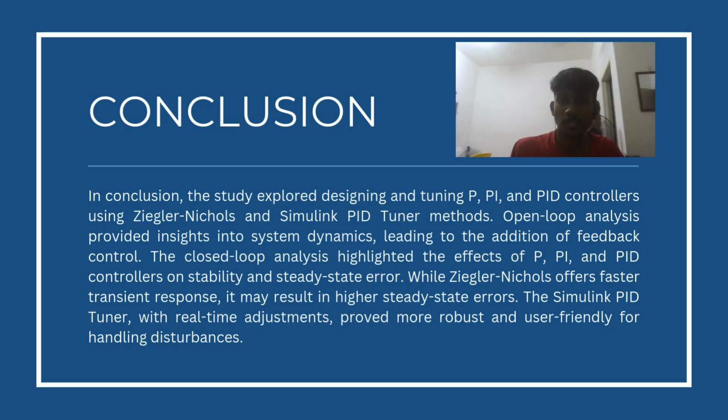In conclusion, the study explored designing and tuning PI and PID controllers using Ziegler-Nichols and Simulink PID tuning methods. Open loop analysis provides insight into system dynamics. The closed loop analysis highlighted the effect of PI and PID controllers on stability and steady state error. While Ziegler-Nichols offers faster transient response, it may result in higher steady state errors. The Simulink PID tuner with real-time adjustment proved more robust and user-friendly for handling disturbance and error as well.